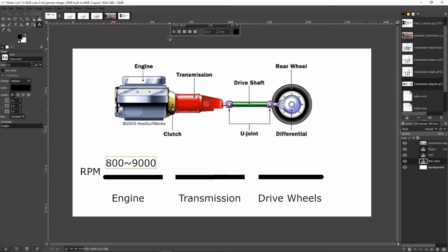This is a really good way to ruin an engine, misshift, and then the RPM goes through the roof. But I wanted to talk about how and why that was happening. So in those videos where the guys were drag racing, we can assume that they were shifting with the engine probably at its RPM limit. And the idea is when you shift up into the next gear, that should create a situation where the engine can engage at a lower RPM, so you can again run through the engine's power band.